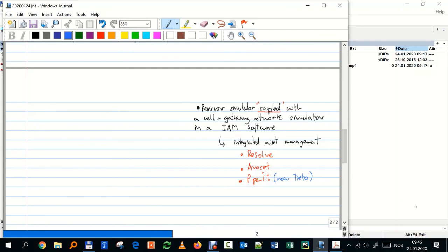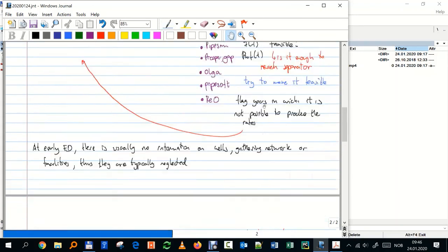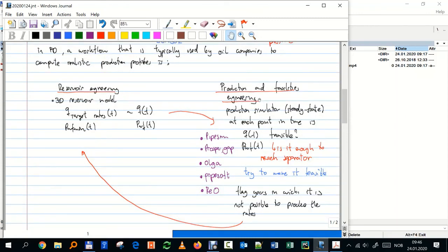But as I told you, that might be challenging, especially in early field, because you need to have a model of this part which might not exist. There is a big uncertainty around it. What kind of well size, how spread are going to be the wells, what will be the topography of the seabed, what will be exactly the water depth, what is separator pressure, for example. The sizing of the lines. All of these require a lot of engineering work based on information that is not available at that point in time.